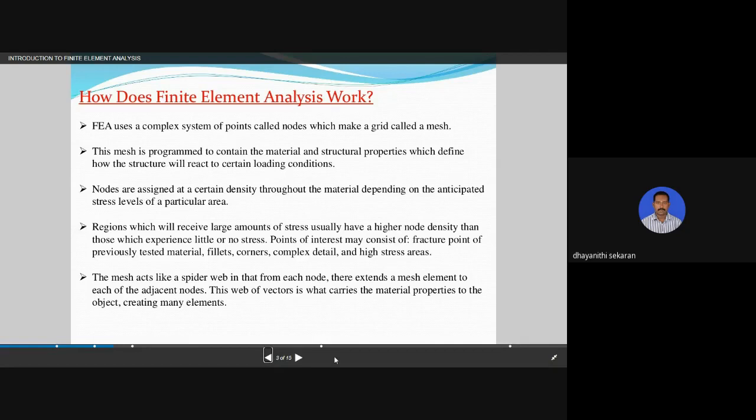We know the general steps of FEA. First one, we need to recall now because one week is over, so we forgot it. We need to recall general steps of FEA. First step is discretization of the structure. That means the art of subdividing the structure into a convenient number of smaller elements. This is called discretization. What are the elements available? One dimensional element, two dimensional element, and three dimensional element. One dimensional elements are called bar element, beam element.